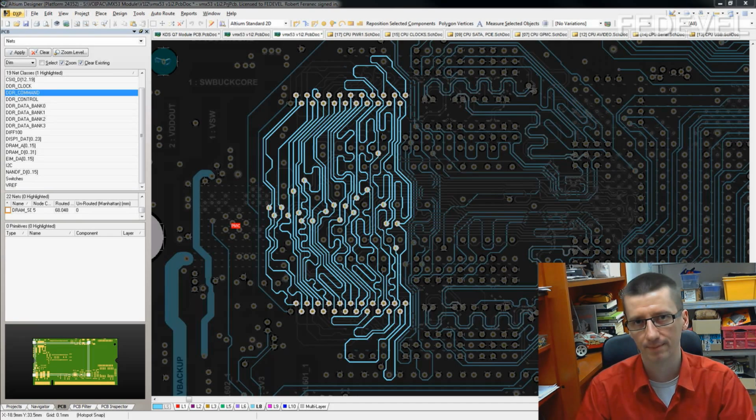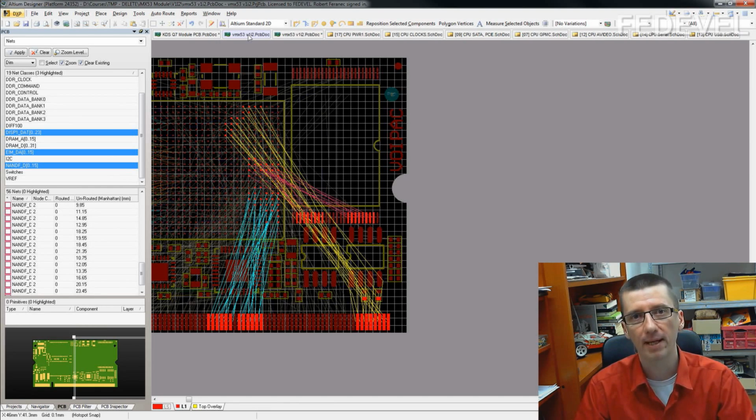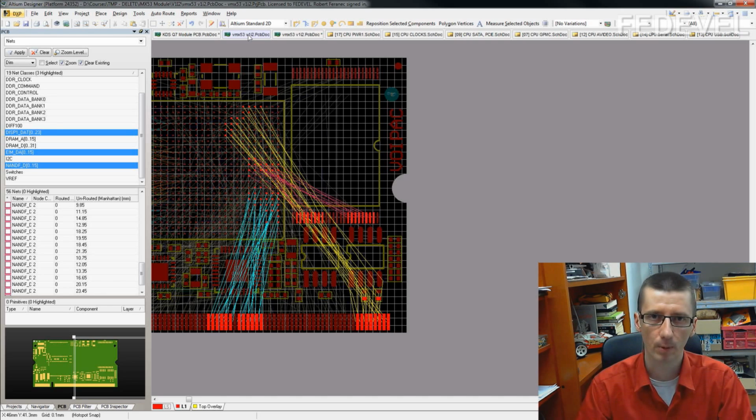Two tips. At this stage of the layout, don't worry about perfect tracks. Just draw the tracks somehow. It's okay if there are some loops or if they don't look nice. You will be moving them and redrawing them many times. So just connect it. The goal is to connect all the pins in some kind of good and proper way.